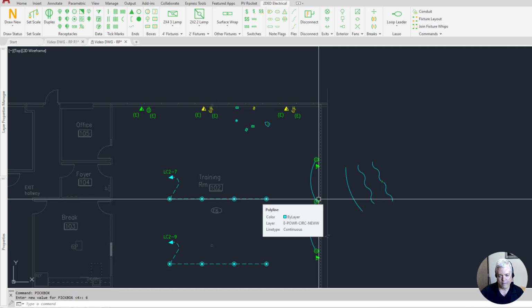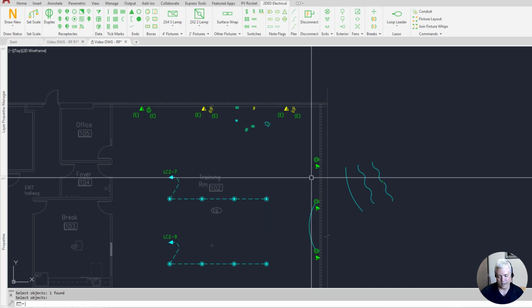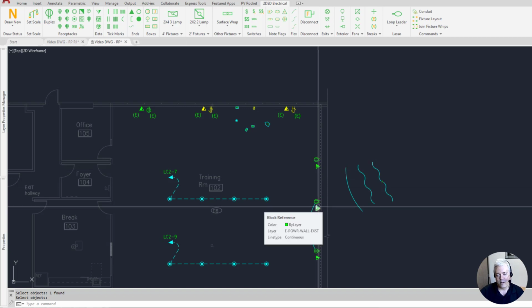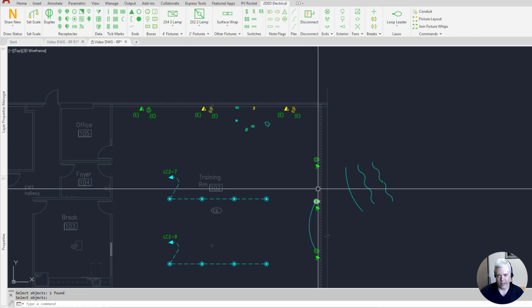My other product, PV Rocket, I recommend 4, because when you're dragging the DC string through a field of modules, you don't want to accidentally get the row above or below, and 4 seems to give you that good control. But here for this ribbon, 6 seems to do a better job. And you don't need to be zoomed in that far anyway.